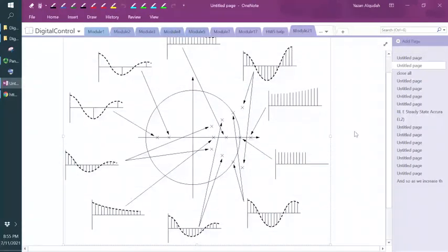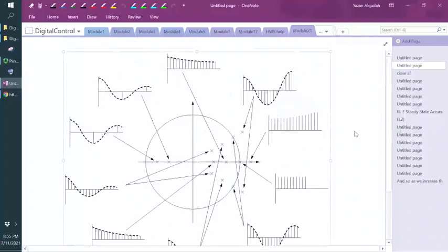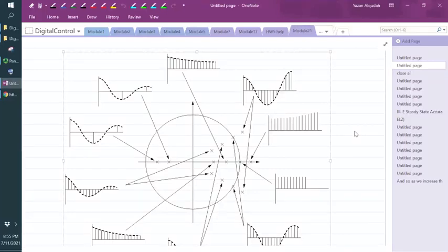In the previous module, we looked at the response characteristics of the discrete time system, and there is a nice graph in the book that shows the different characteristics of the response depending on the location of the pole of the system. As you can see in this graph, if the pole is at negative 0.5, then the response of the system is going to look oscillatory, oscillating between positive and negative. If the pole is at 0.5, it's going to be just a decaying exponential response.